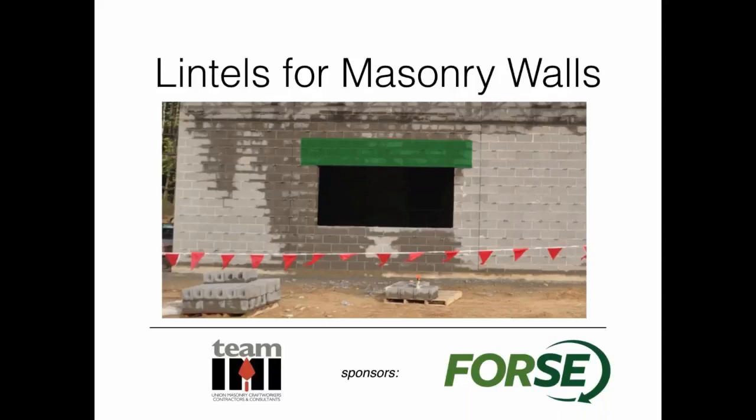So I really struggled with it because I think there are so many different ways to look at why masonry lintels make so much more sense than steel lintels or precast lintels. Why you can really leverage your design of masonry so much more. So that's really what this talk is about. It's really trying to help you guys navigate towards why these make sense, why they can give you so much more capacity, why you can think about even thinning down your walls sometimes, using less grout reinforcing around your openings. There's just so much that you can do when you consider masonry lintels.